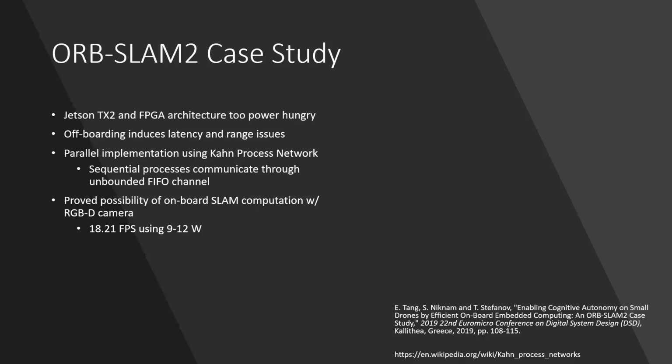Then I also found an ORB-SLAM case study, which is really interesting because it talked through some of the problems implementing on a drone. And so the first one being, you have to write this algorithm and process this data somewhere. And so a Jetson TX2 and FPGA architecture, which are really, really popular for a lot of these different applications, are really too power hungry when we're talking about trying to use 9 to 12 watts.